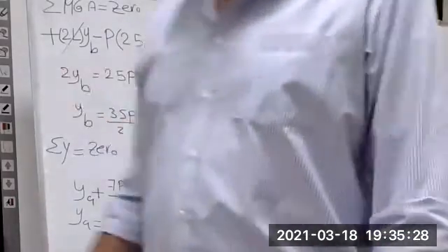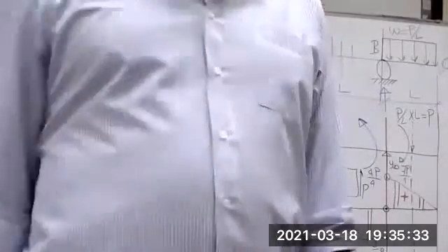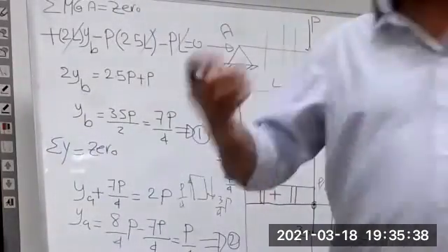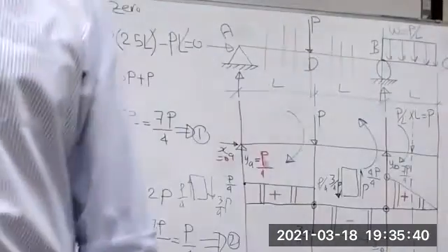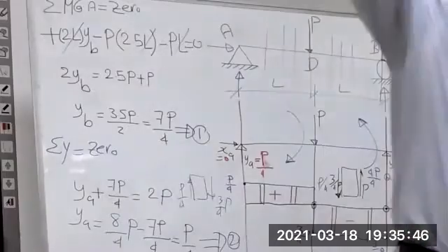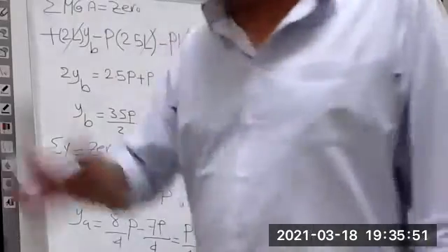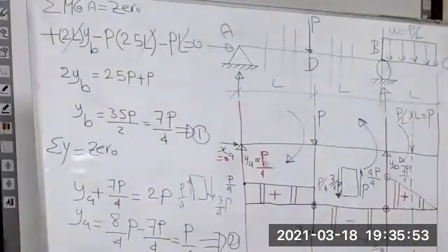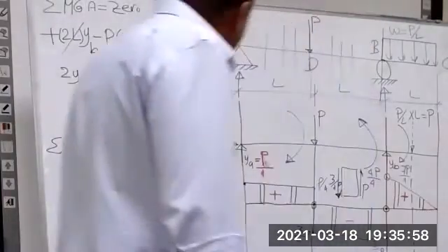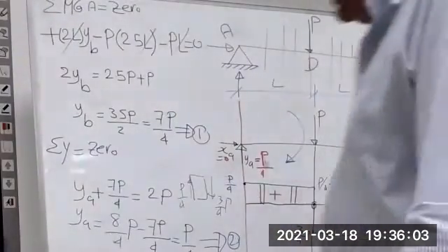Why do we draw the shear force diagram? To get the maximum shear force. Why do we need the maximum shear force? We need it to calculate shear stresses. Why do we need shear stresses? To check our design of concrete and steel bars. One by one: from structure analysis to steel design, to concrete design, to foundation. We have to understand now. I will draw the moment diagram, how it will look. I will erase this one, please, guys. Okay.